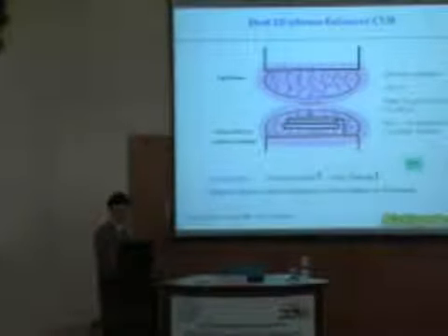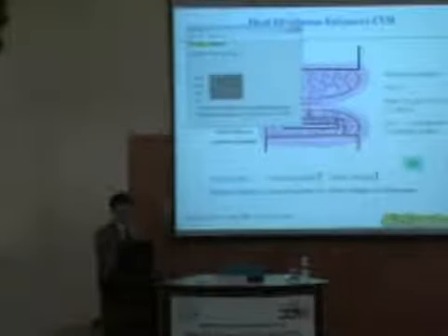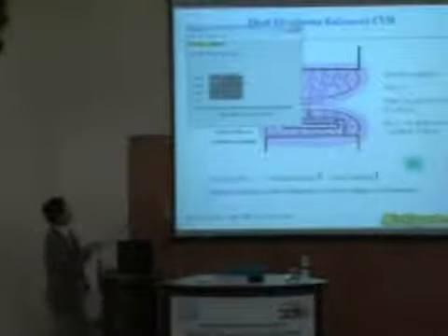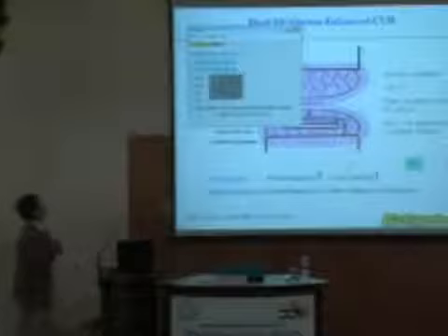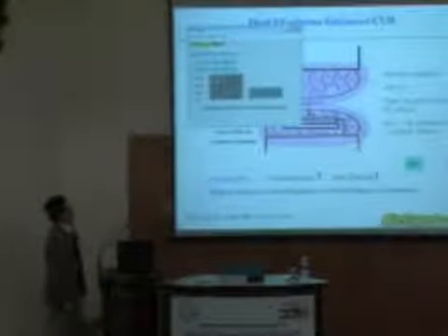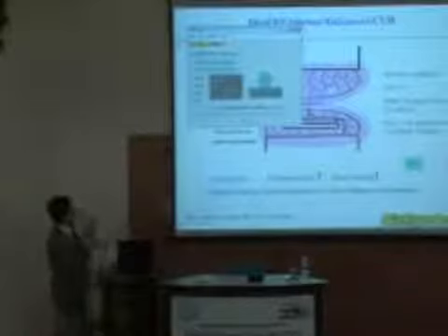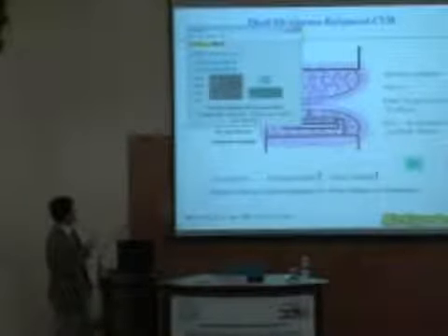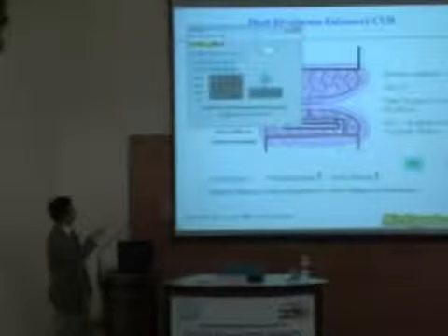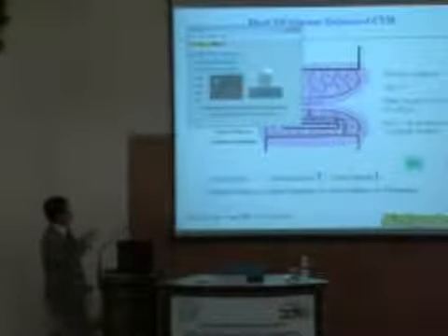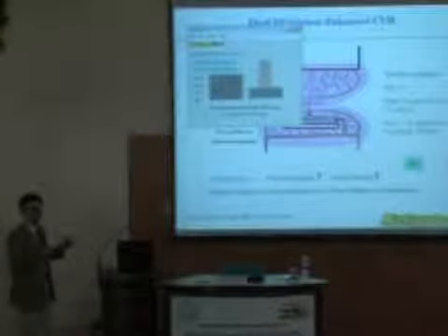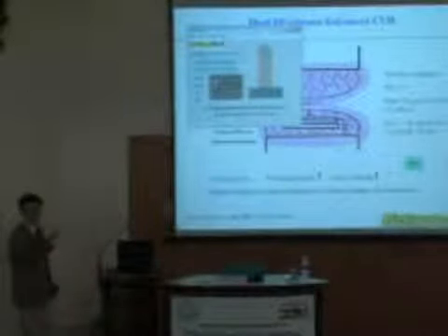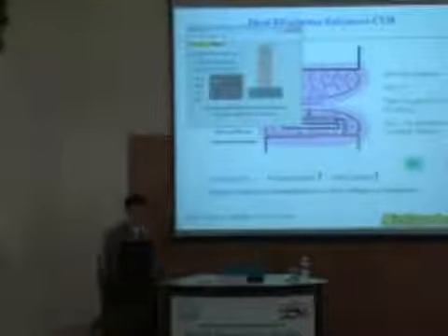Let me quickly show you how the whole process goes. Basically, you start with a catalyst on a substrate. This catalyst is nickel, and when you heat up the substrate, part of the catalyst will start to melt, and you use the plasma to generate a growth species to shower down, and this carbon species will dissolve inside the catalyst. When this catalyst becomes saturated, the carbon nanotube will start to segregate out from the catalyst and form vertically aligned carbon nanotubes, as shown here. A very quick cartoon.